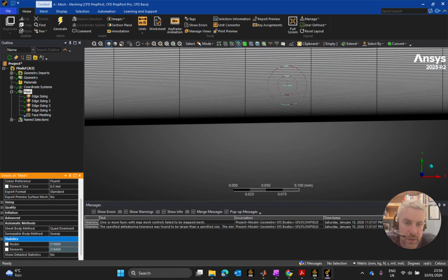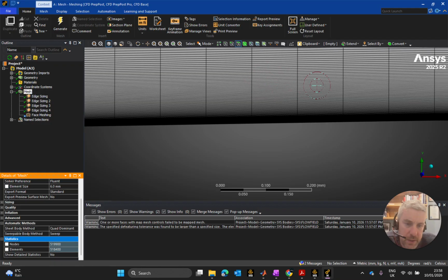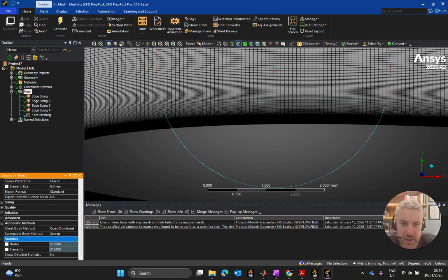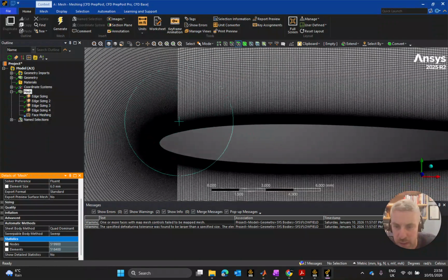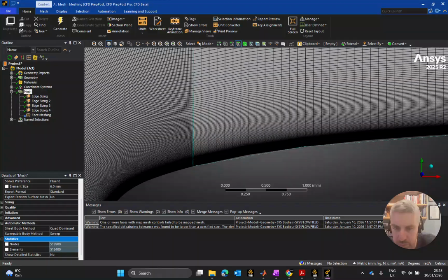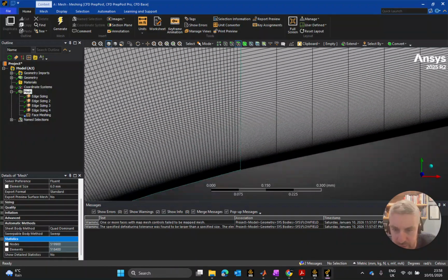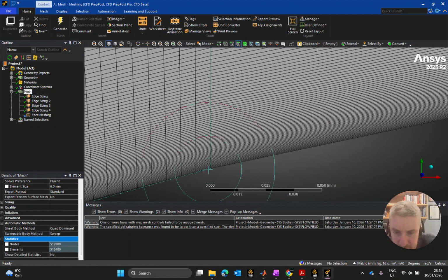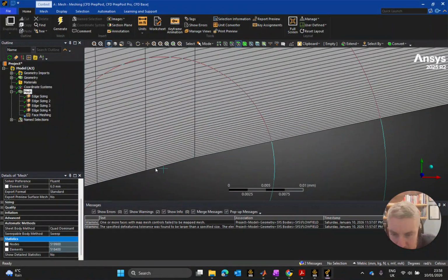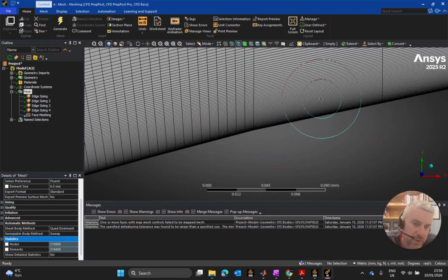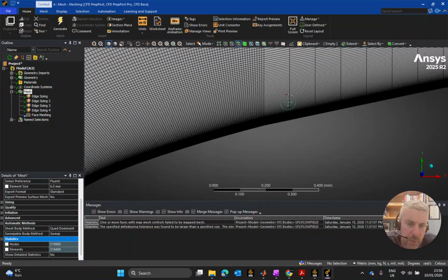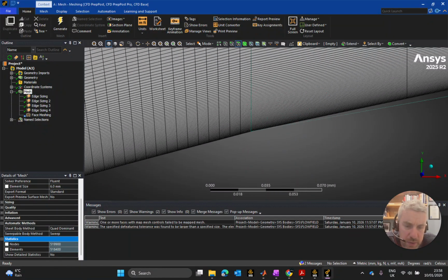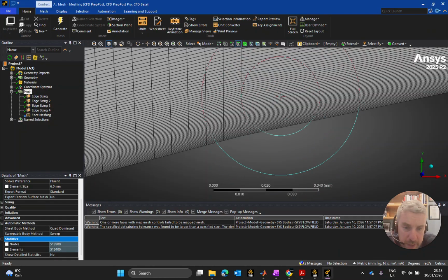What I'd nearly need to do is make these divisions here a lot closer together, to try to improve the quality of that mesh. Whereas if you compare that to the front, those are very nicely shaped ones there. Obviously, it's not as critical along these areas because that's the direction that the velocity is moving. We're not crossing over them. They're running with the shape of the velocity, but I probably can add more divisions here, or else I can reduce the bias slightly.